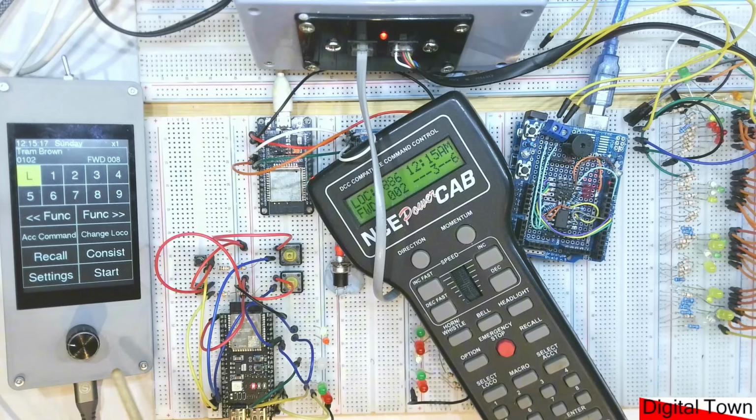on your NCE system. However, there are certain limits to the power cab, not the bigger systems, but obviously the power cab, you're limited to 1.5 amps unless you put a booster on it. I recently built myself a nice little 5 amp booster, cost me about £6. So it's very easy to add a booster to the power cab if you want to do it, but you are still limited to a certain number of locos from what I can remember.